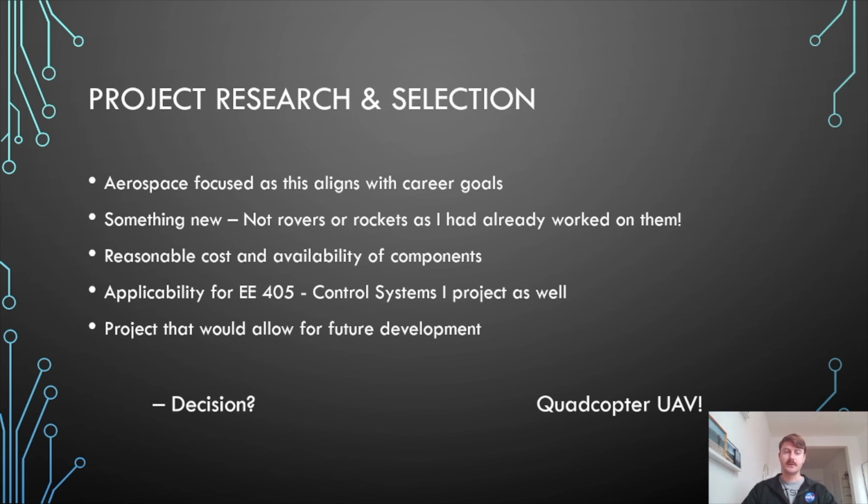Control systems applicability was important, as well as cost and availability of components and the potential to develop further. With that, a UAV was decided on. I considered a fixed wing UAV, but the linear distance needed for takeoff and landing would have been harder to access here in downtown Montreal, so a quadcopter, the traditional drone that you think of, was chosen.